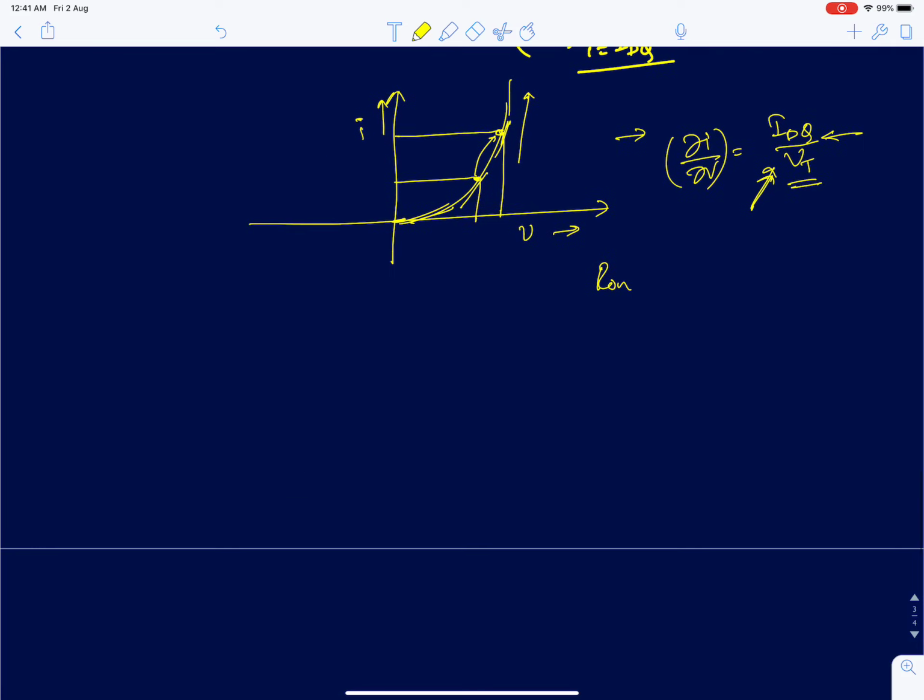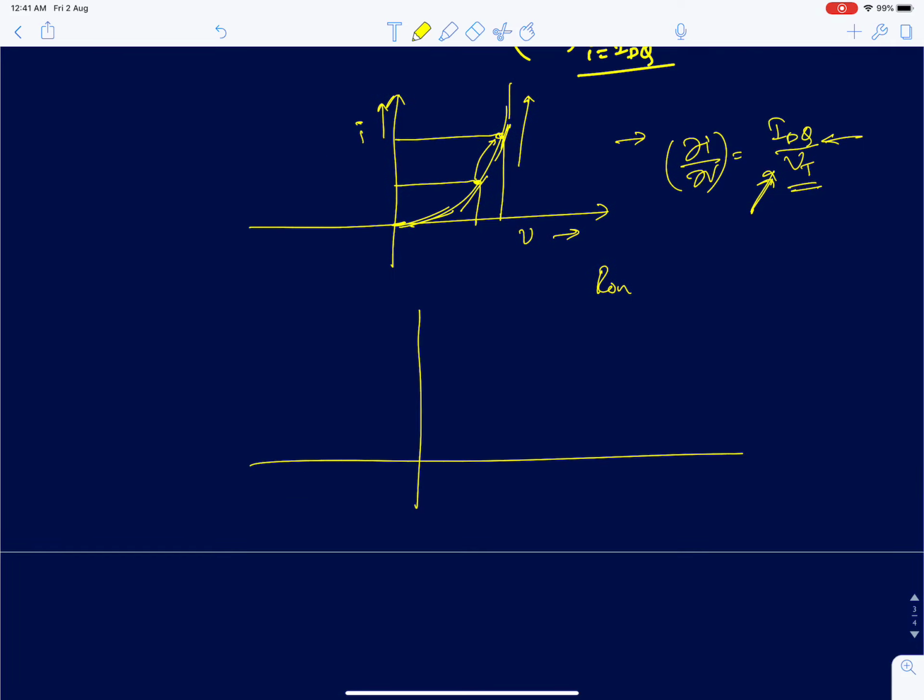So when I'm going to use a straight line, that is a linear line, to model a diode resistance model, of course the model will work for a small range, but it's an exponentially increasing function. So eventually the model and the actual diode equation, the error between the two will start diverging. And I think I've discussed this in the last class.